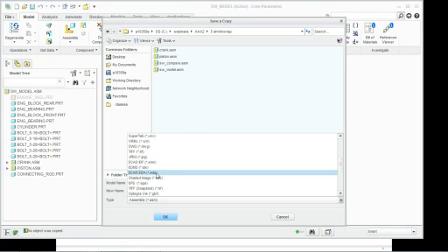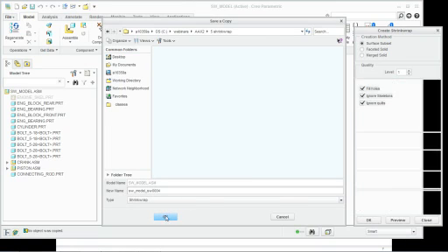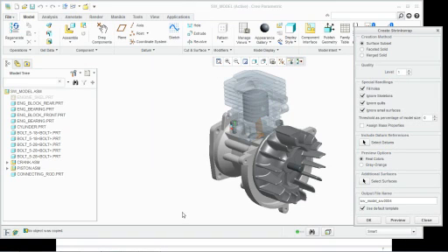Yeah, they couldn't put these in alphabetical order, could they? There we are, Shrink Wrap. So we're going to leave that shrink wrap model SW.004, and I'm going to click OK, and in the dialog box I'm going to say I want to fill the holes. I want to make sure I assign mask properties, so we're going to check that. And then down at the bottom I'm going to say I want to use gray and orange color.